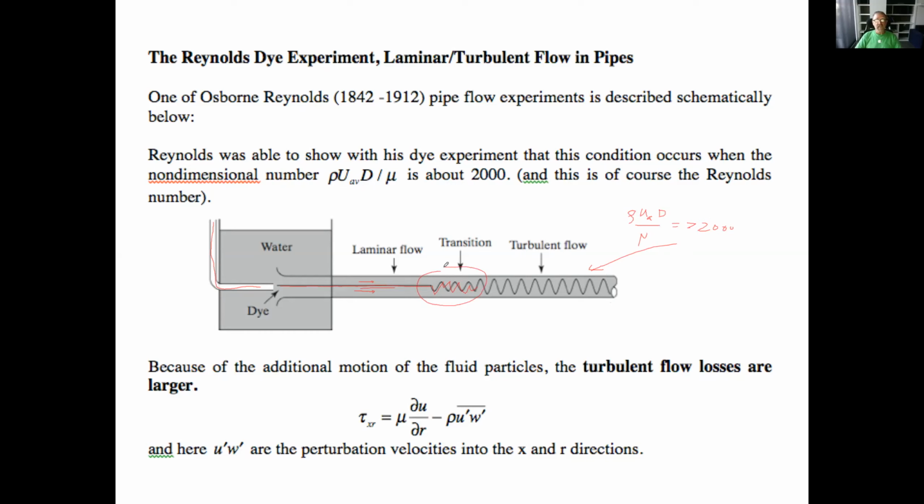Okay. Now, the moment you have transition, you naturally start losing more pressure. And here is some, because the molecules are starting to move to the side and then more impingement on the wall. Turns out also the shear is larger. So in general, in turbulent flow, the friction coefficients is significantly larger. And it's true also for external flow, like an airplane. You've heard the story about laminar wing, turbulent wing. If the flow is turbulent, the friction is significantly larger.